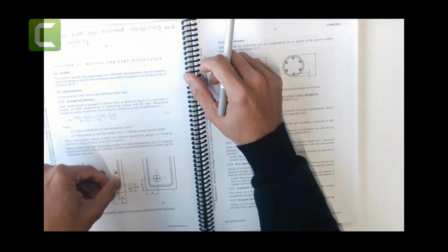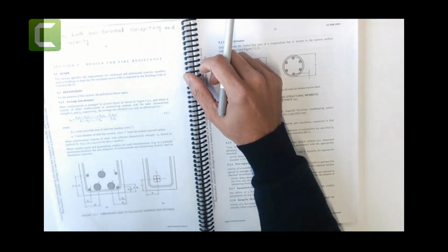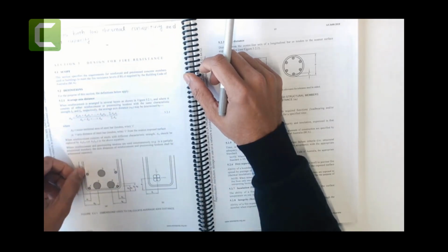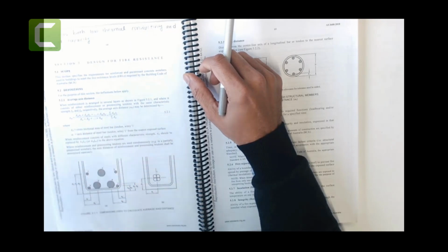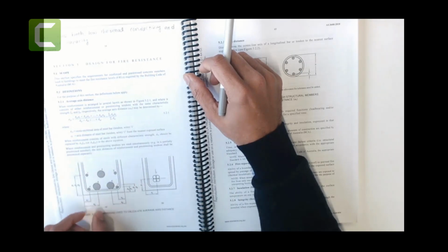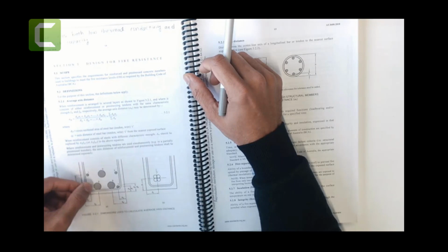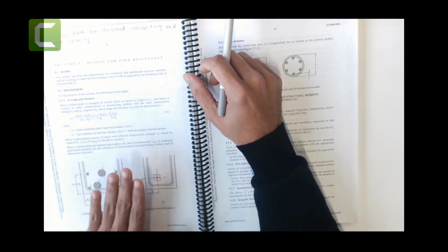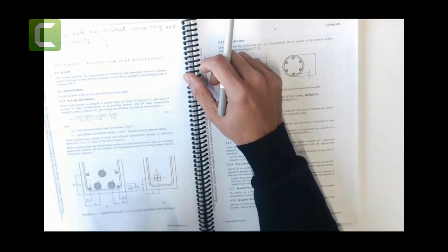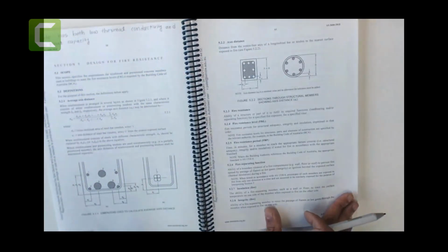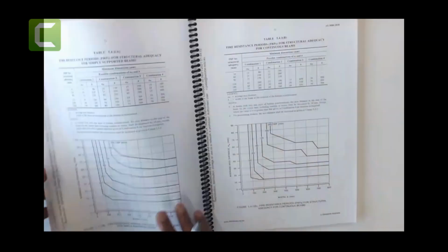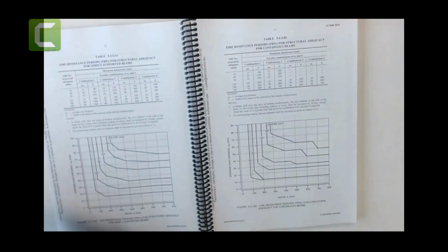This is the fitments. Probably when you do the workshop and the test, we will show you the fitments in the real world. And these are the main longitudinal reinforcement, and this is the concrete. And this is the cover. The standards will specify this axis distance from the center of the bar to the outer surface of the concrete. And then we can calculate the cover from this and these fitments. Now, let me take you through the first beam.